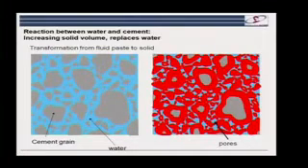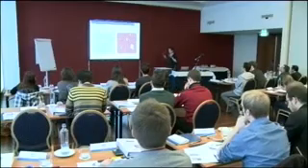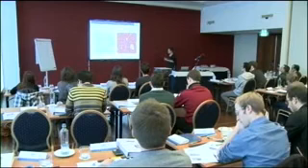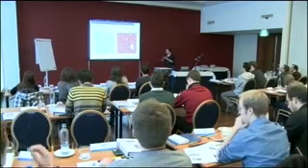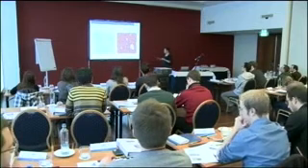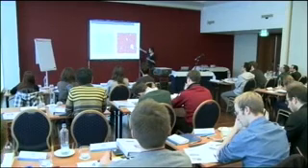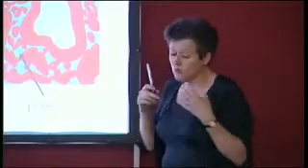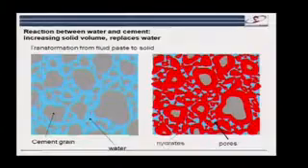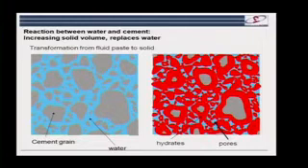this hydration. So now we're going to just see some very basic diagrams of this hydration, because this is the whole process that's going on that transforms our fluid concrete that we can put in place into a solid. We get this grey material, the cement grains, reacting with the water to form a new product. That's the red stuff here, which is the hydrates. Okay? So that's a very, very basic scheme of what's happening that we're going to talk about in more detail later on today.